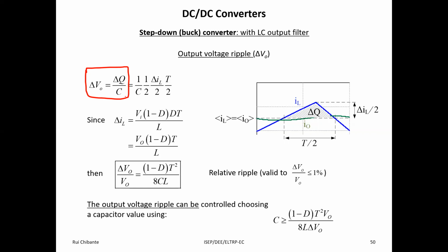And since the charge in a capacitor is the current that flows along the time, that is equivalent to an integral, and we can see the integral as an area that we can calculate. So again, from this picture of the currents, what we are doing here is to say that this quantity of charge corresponds to the area that is represented here.